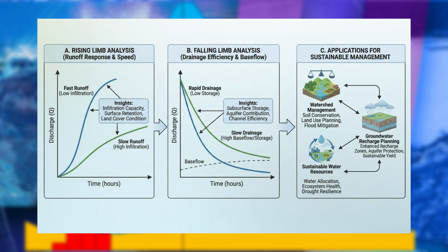Beyond structural designs, hydrographs provide valuable insight into the overall functioning of a watershed. By examining the rising and falling limbs of a hydrograph, hydrologists can assess how quickly rainfall is converted into runoff and how efficiently water is drained from the basin. This understanding supports better watershed management, groundwater recharge planning and sustainable use of water resources.